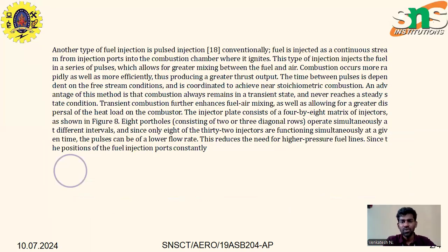Conventionally, the fuel is injected as a continuous stream through injection ports into the combustion chamber where it ignites. This type of injection, pulsed injection, injects the fuel in a series of pulses, which allows for greater mixing between the fuel and the air. Combustion occurs more rapidly as well as more efficiently, thus producing a greater thrust output. The time between pulses is dependent on the free stream conditions and is coordinated to achieve near stoichiometric combustion.